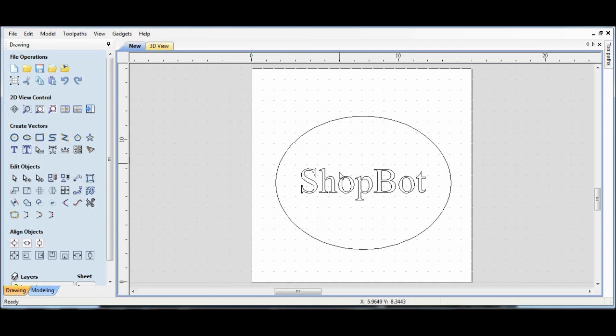So this is very, very basic, but sign making on the ShopBot is wonderful. It's fantastic, but it is actually surprisingly easy to do. So we have this. It's very easy. We have our shapes now. I got my outside profile that I'm going to fully cut out, and then I have my inside lettering that is just going to be etched onto the top. So that's all I want to do with this. Obviously, we can get as crazy as we want with this, but for this class, this is good enough. So I have created my design.